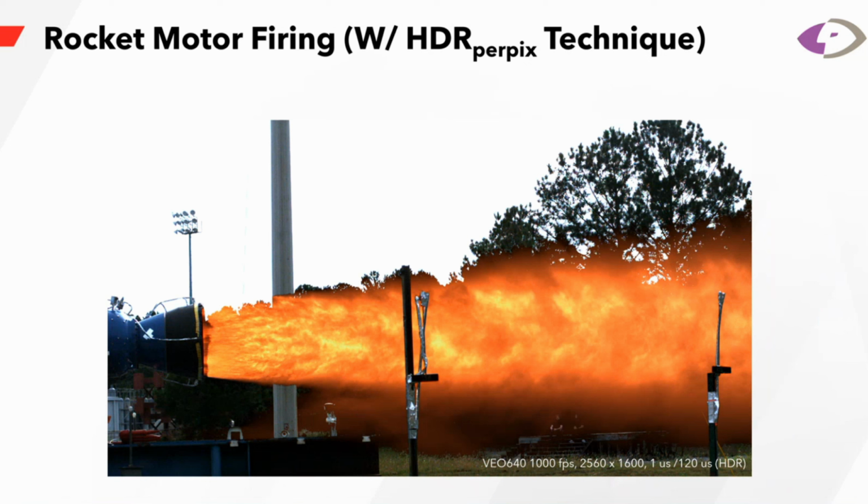So what we simply did was we took 2 cameras, synchronized them at frame rate, had one camera set to 1 microsecond, the other set to 120 microseconds, and we simply used a Python script to combine the frames in post to result in a video that had a much higher dynamic range, hence the HDR technique. This can be easily done using any stereo pair of cameras that are synchronized.